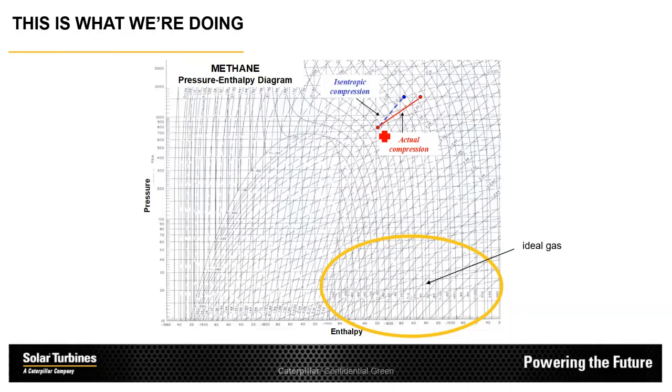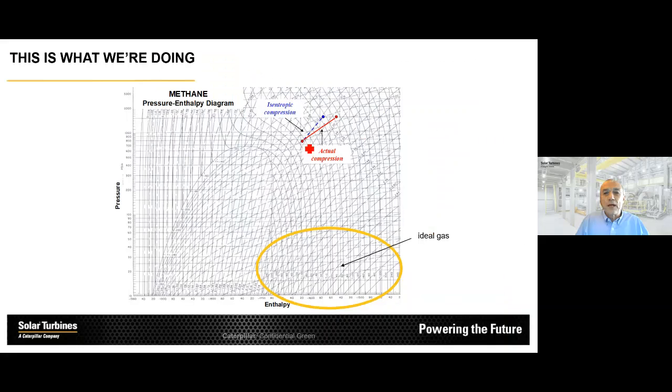and it is actually a very good way of starting the discussion because for many processes, you know the suction and discharge pressure, and you know the suction temperature, but you don't know the discharge temperature. So with the ideal process, with the isentropic compression, I start at my suction conditions, and then I go to my discharge pressure along a line of constant entropy.